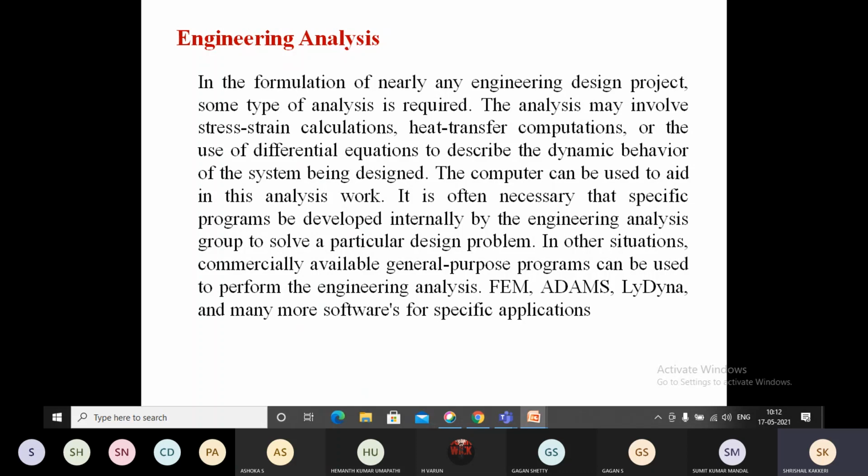So this 20 mm square of 100 mm length, I may create it for wood, I may create it for steel also. And I have to give the input parameters: is this steel or wood? In what way am I going to give it? Already in the 3rd semester we studied the stress strain analysis using the universal testing machine. So the Young's modulus of the material will be inputted. And I may have to go for the stress strain calculation, or the heat transfer calculation, or some other calculations.